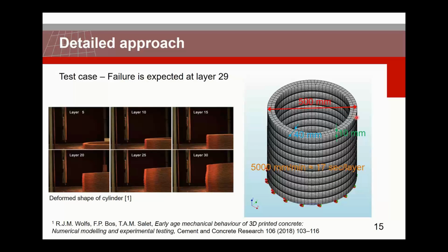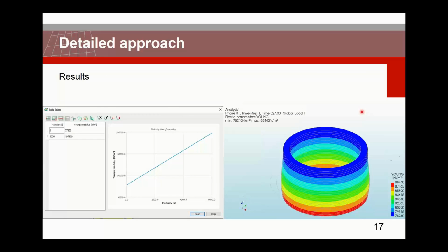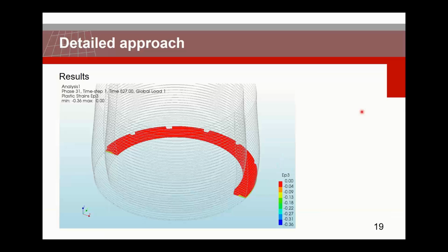That's probably also one of the reasons why the convergence behavior in the end is a bit poorer, because this is not enough to describe buckling over this thickness. In general, we advise using around 4 elements over the thickness to describe buckling. But in this case, I only used 2 to speed up the analysis a little bit. But this is probably also one of the reasons why the convergence is a little bit worse towards the end.